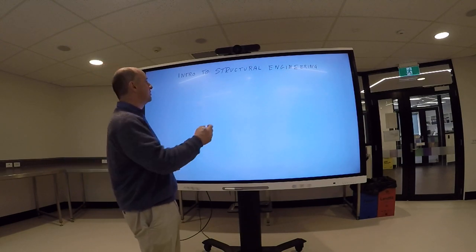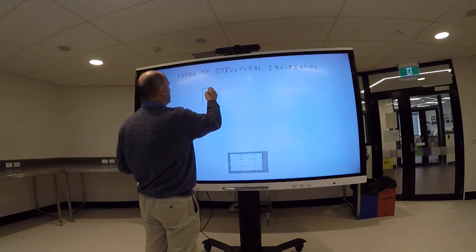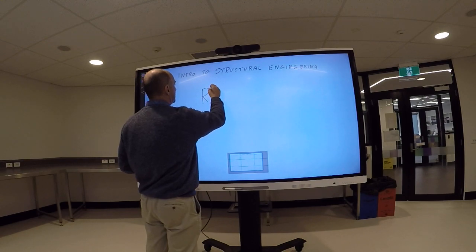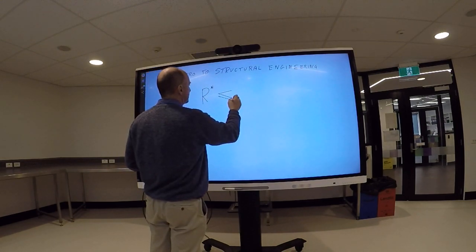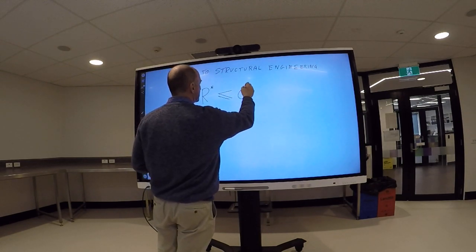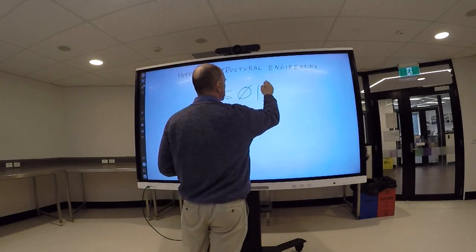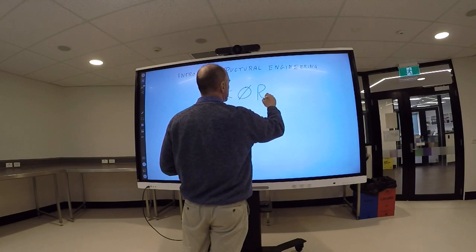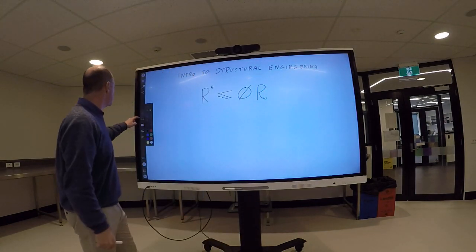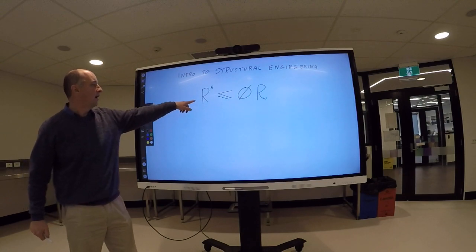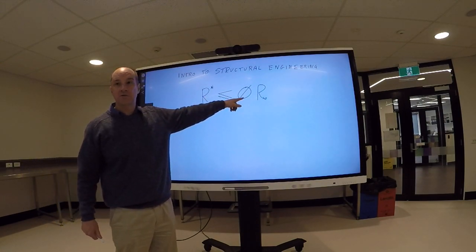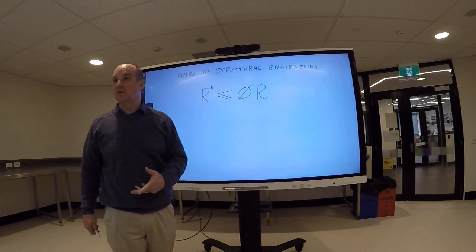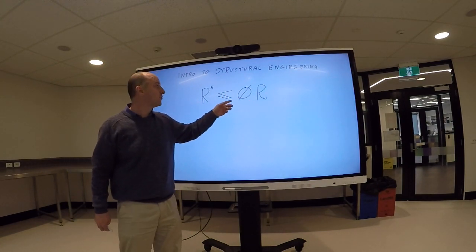So I'm gonna put a basic equation up here, which is R star must be less than or equal to phi R U naught. Okay, R star is an action. Phi is a reduction factor, R U naught is a capacity. Okay, I'll talk about each of these in detail.